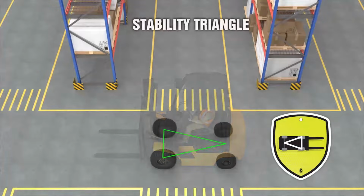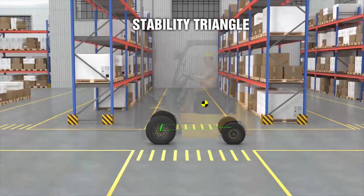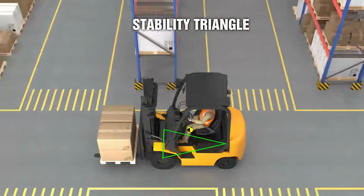The teeter-totter concept is a good start. Here's another key tool you should use, the stability triangle. Imagine a triangle placed between the axles. Points A and B are a straight line between the front tires. Point C is centered on the rear axle. This triangle holds your safe center of gravity. When unloaded, the center of gravity is located around the middle of the forklift. Adding a load, moving it up or down, and traveling with it shifts the center of gravity.